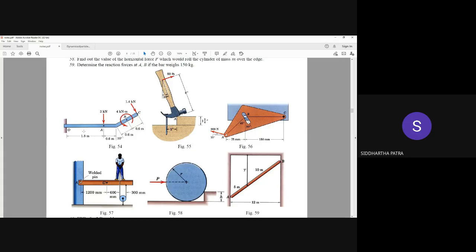I'll be removing one support and then substituting it with something. And as a substitute, I'll put the corresponding reactions, be it forces or moments. So the free body diagram has the rigid body of our attention, and then we have the reaction forces and moments coming from the support, but not the support itself. Having the support as well would make it an incorrect free body diagram.